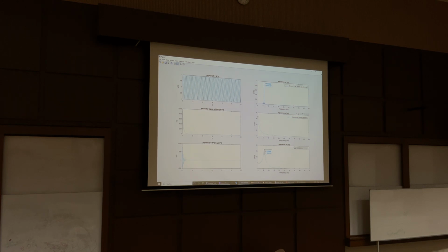And this amplitude here at the very beginning, that is my decaying. Amplitudes are not important here at the moment because it's not an ideal one-to-one Fourier transform. It is a fast Fourier transform, and that takes into account that there are adjacent values, and these adjacent values would sum up to the amplitude here, in this case of 34. Okay?